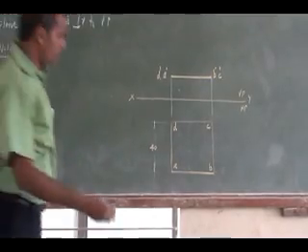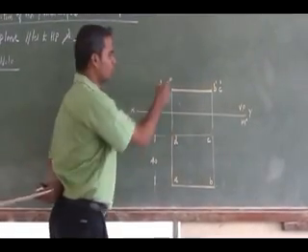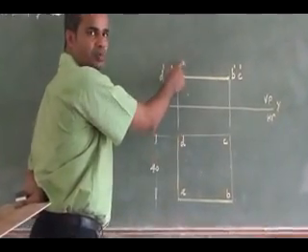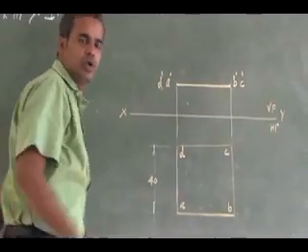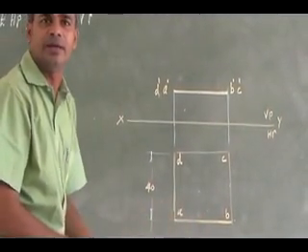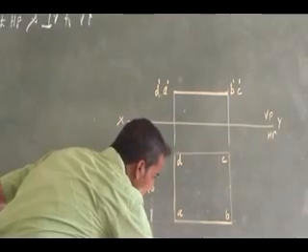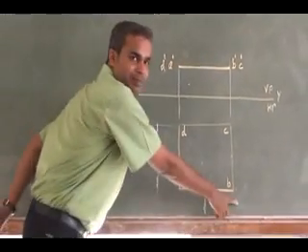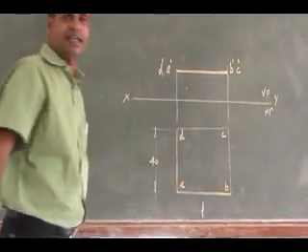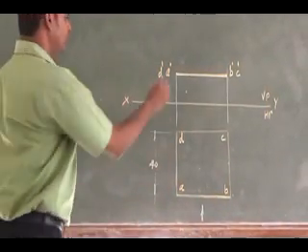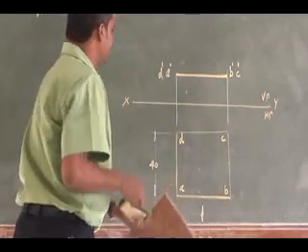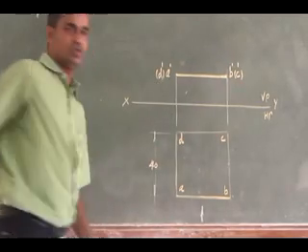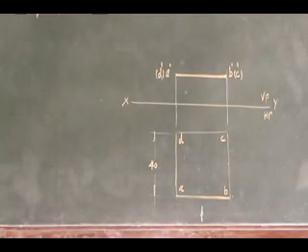To mark the hidden details in the front view, you have to look at the top view from the bottom. While looking from the bottom, I can see A and B, I cannot see C and D. So C and D are hidden, and I put them inside brackets. So this is how you have to finish the problem.